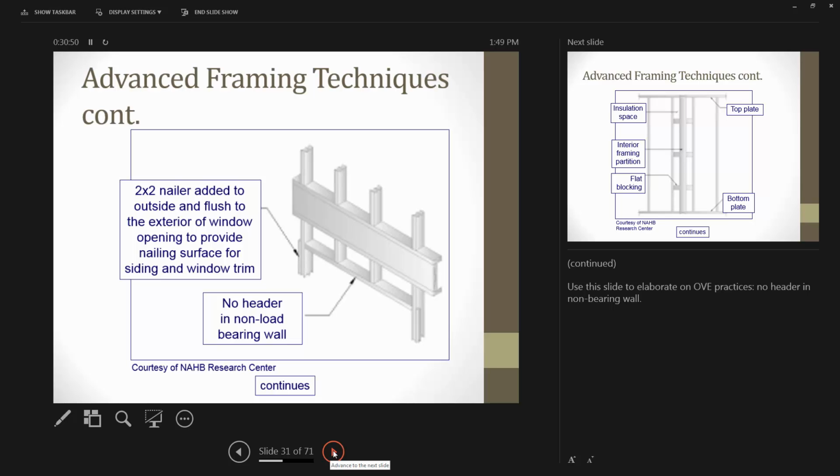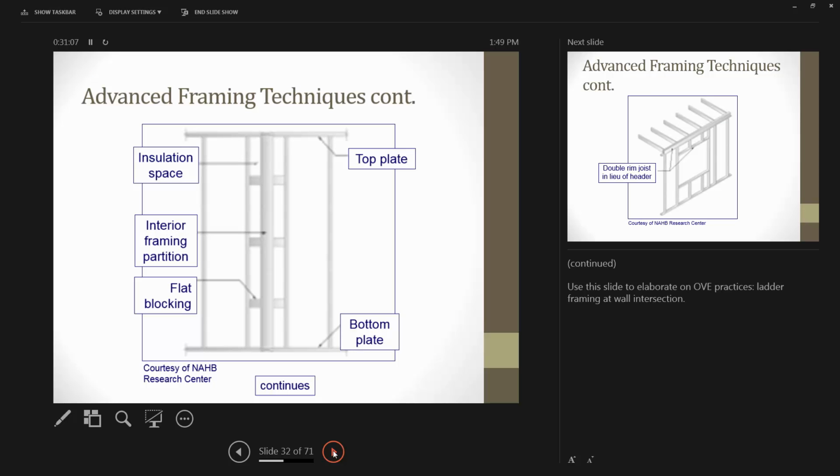You'll even find now 2 by 6 on 24-inch centers, depending on how, we won't get into shear nailing and attachments and shear wall structures, but you can reduce the amount of wood in the wall pretty significantly and raise the efficiency of the house.